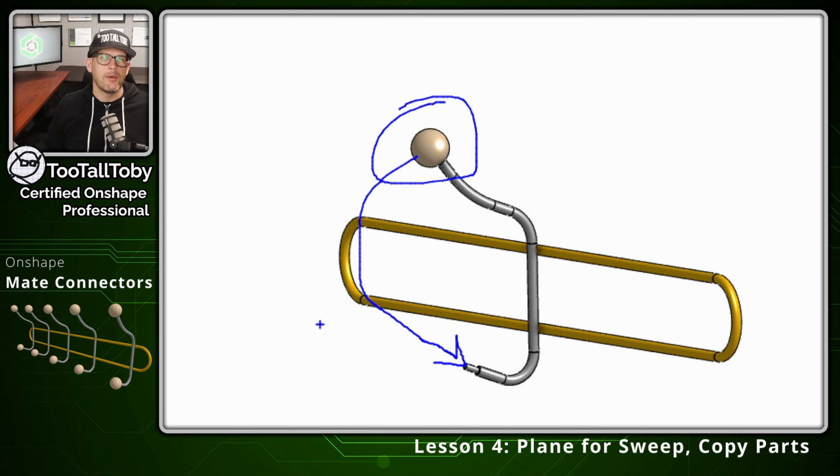I can't do it with a pattern. I can't do it with like a linear pattern or a circular pattern. And so what do I do? Do I maybe just create a new sketch down here, create another sketch of that revolved shape, and then revolve that about an axis to create that second wooden ball? That's actually how I did it the first time.